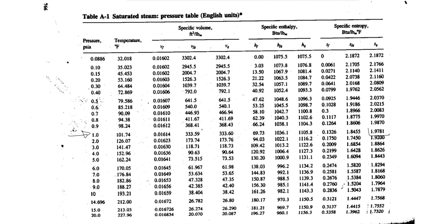At 1 psi, the value of Sg is 1.9781, while our own value, S1 equal to S2, was somewhere equal to 1.569 or something like this. So our value is less than the value of Sg, so we are inside the vapor dome, or we are in a saturated region.